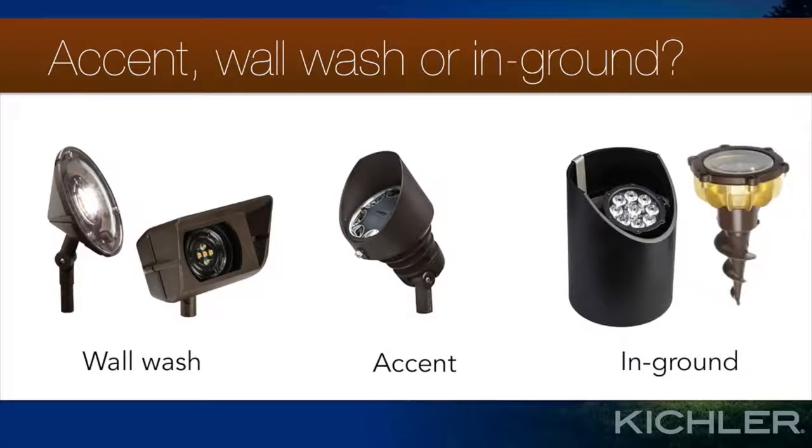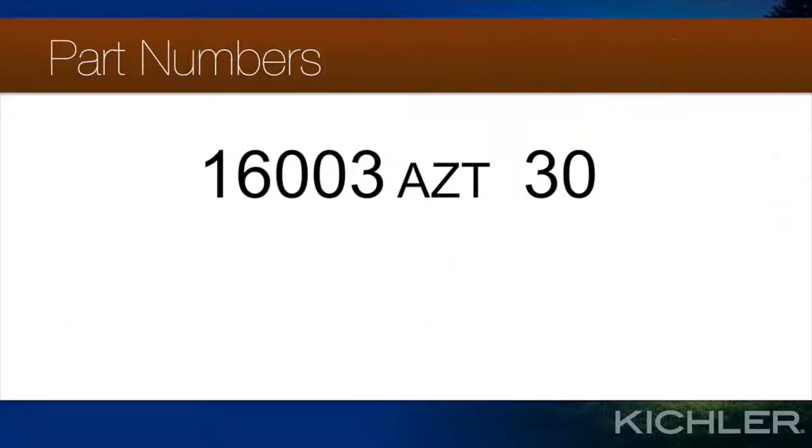In-ground lights are often used in situations where accent lights might be damaged, or where you need to keep the fixture out of view for aesthetic reasons or to reduce glare. In-ground lights can be aimed just like accent lights, but don't have the range that accent lights do. They can be adjusted about 15 degrees as opposed to accent lights' 115-degree adjustment range. There are two basic types: in-ground lights that screw into the soil and those that rest in a can that is buried. You can also mount in-ground lights into concrete, sidewalks, driveways, or patios using a concrete kit.